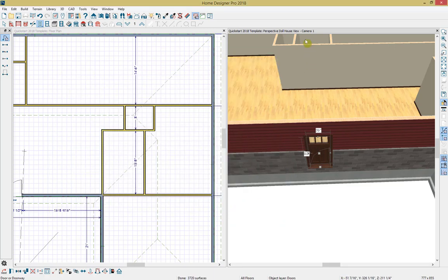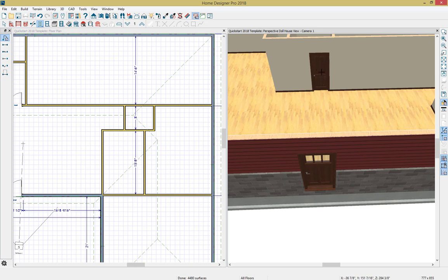And then let's go ahead and add a door into the interior side of our plan. So let's go back to that door tool, and then just drop a door where we feel is necessary. And notice that this program recognizes that this door is placed in an interior wall, so it's going to be an interior door, whereas this door should remain an exterior door.